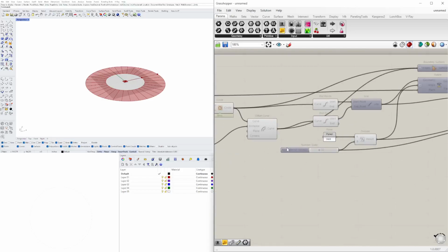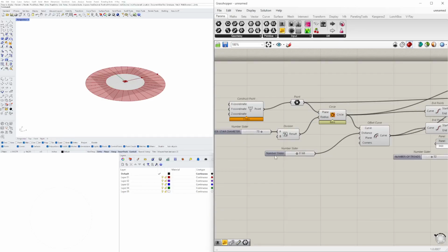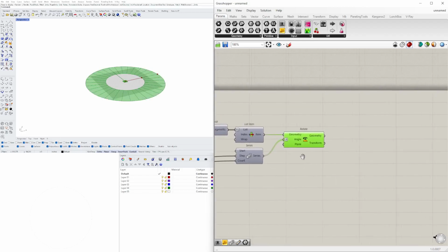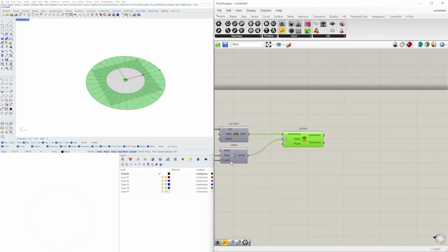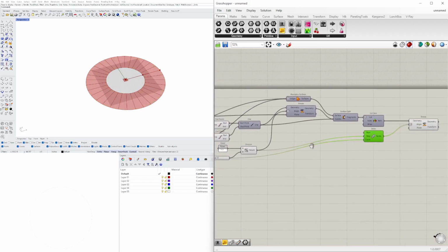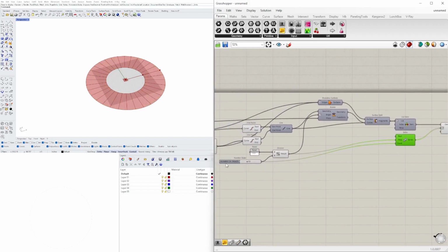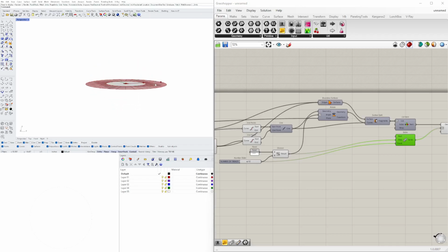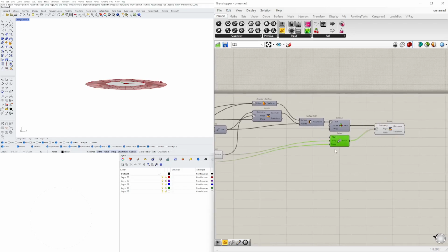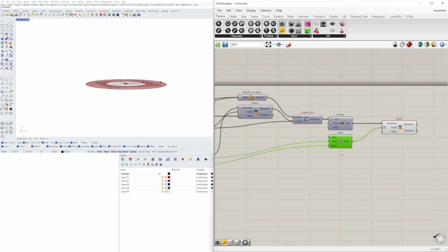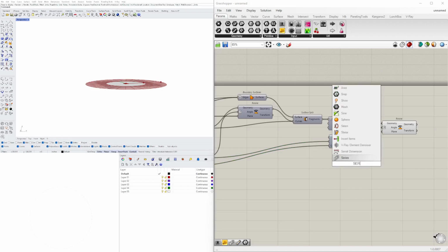All right, so at this point, we got most of the stuff. Now the only thing I haven't relabeled here is going to be stair width. Okay. Now what we need to do is the same thing that we did with series, because we know how many treads we want. So now we need to move it up vertically by 32 times by a specific height. So series is exactly what that's used for. It's, for me, one of the most useful components.